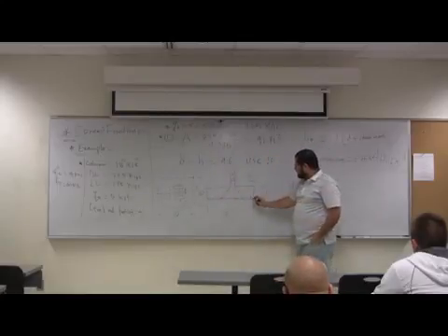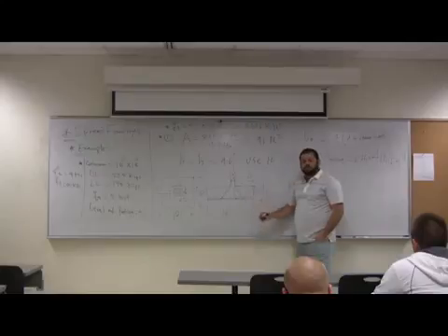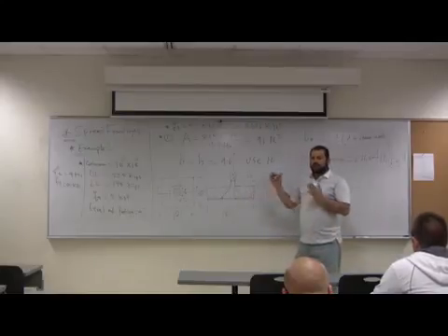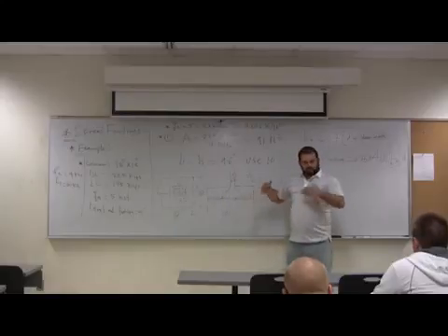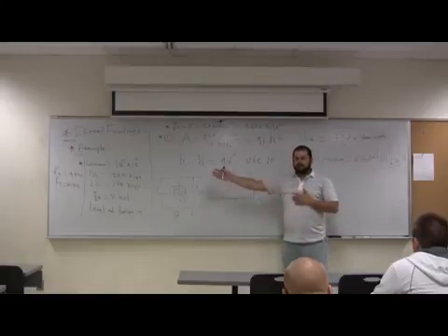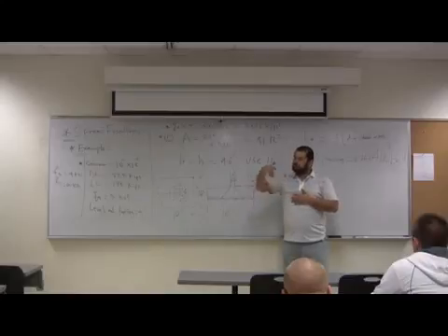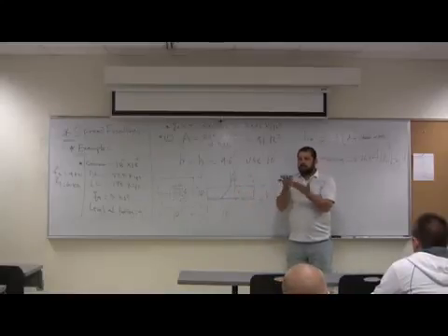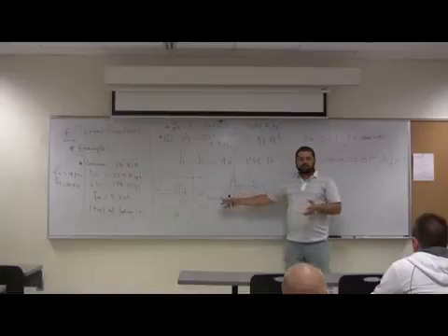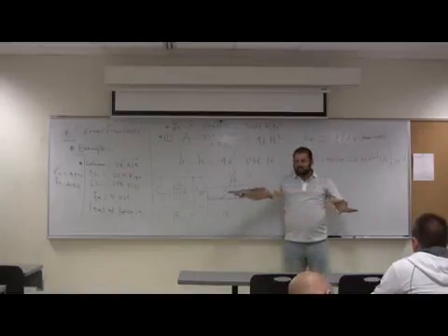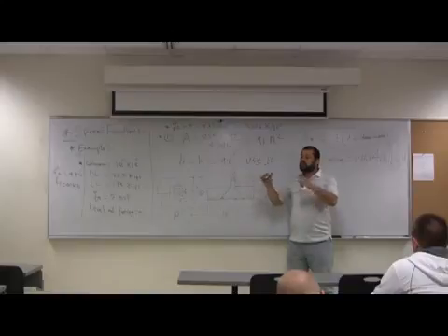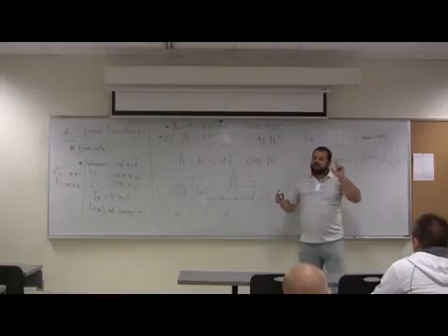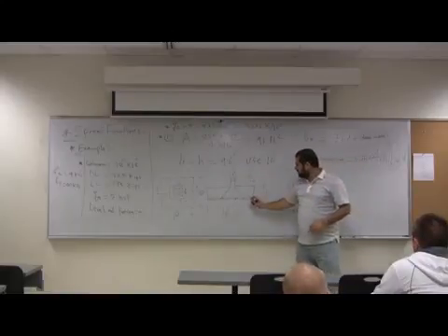We have this steel and this steel at the top. They're supposed to do the same job. They have to do the same job. They're supposed to resist the same moment. So what you do, you design one and you make it the rest. You design one and you use it in both directions. But when you design one of them, then the other direction is exactly the same. It's a square footing. So which one is more critical? The one with the smaller d, which is the one at the top.